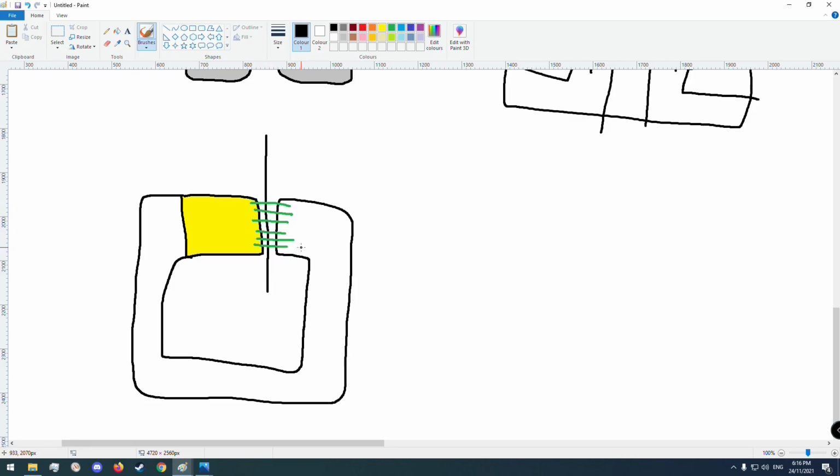Although these speakers, the big fins on them, as much as they'd probably help for cooling as well, they also help channel the flux around back to the rear of the magnet. Although these big fins are probably required, as I mentioned, voice coils can get a lot hotter than 80 degrees Celsius, so you really do want a lot of cooling applied to the neodymium magnet in order to prevent it from overheating and getting past the security point and just stopping, especially for a $5,000 subwoofer. That would be a real shame.